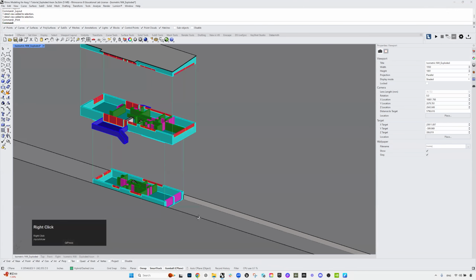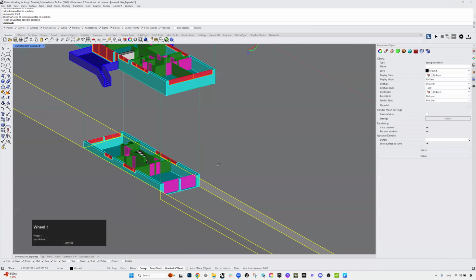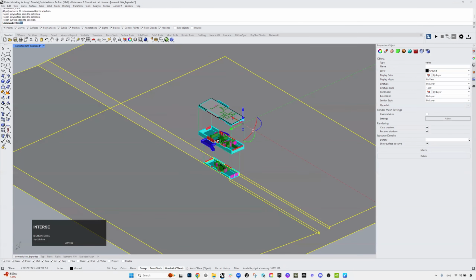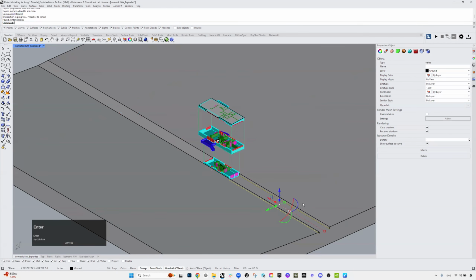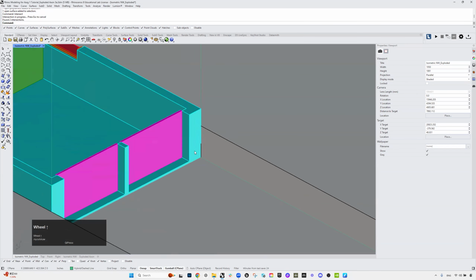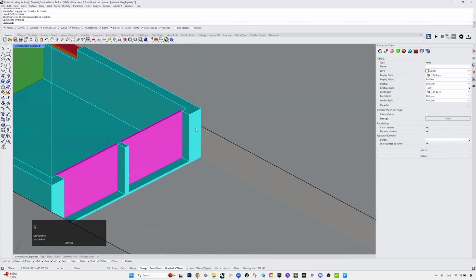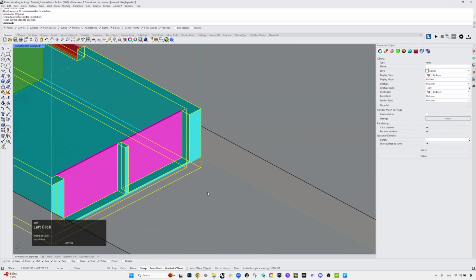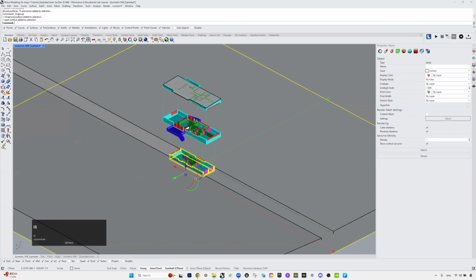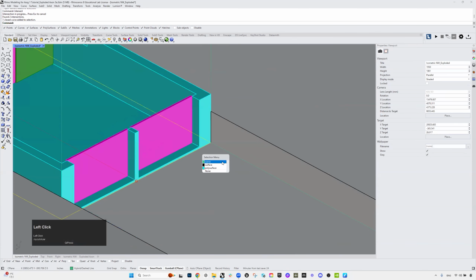Because all these things were missing, first I'm going to select this ground and another ground surface, type the intersect command, click OK. So that creates the lines over here. And I'm going to do the same thing here. I'm going to ungroup this and select this geometry and then the ground geometry, type intersect, and that created the curve line over here.